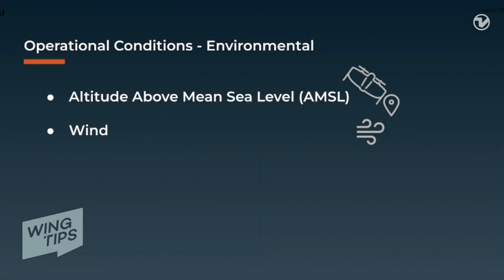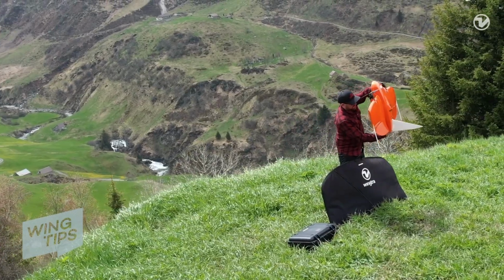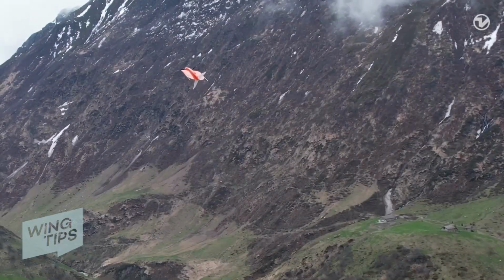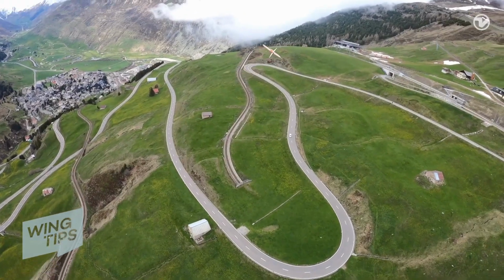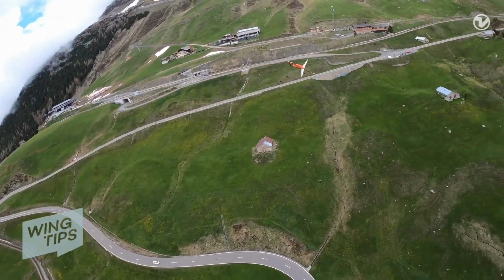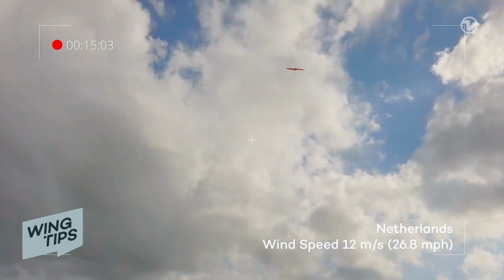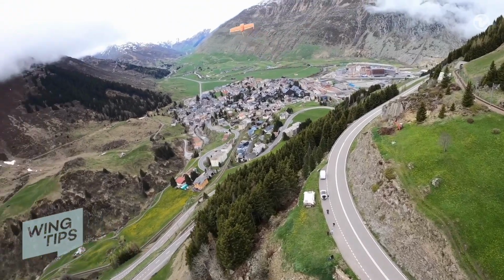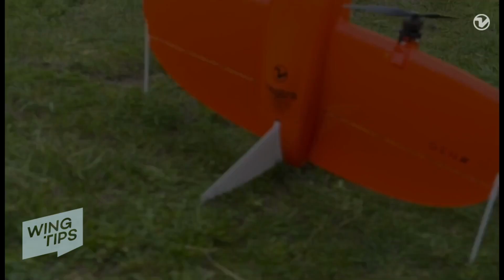Stronger winds cause drones to consume more energy while flying and landing, which leads to shorter flight times. That's not to say that one cannot operate a drone on a windy day. However, wind tolerances must be taken into consideration as they vary from system to system. For the WingtraOne, cruising at an altitude of 120 meters or 400 feet, it will safely operate and capture data in sustained winds up to 12 meters per second or 27 miles per hour and gusts up to 18 meters per second or 40 miles per hour.